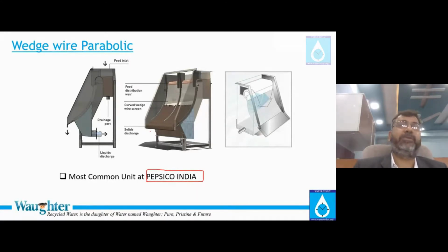If you identify the COD potential of those skins, we are typically talking about a COD reduction by screening alone of almost 6,000 milligrams per liter. So you can compare a waste sample before screening and after screening. And this potato skin is very easy to accumulate on the parabolic screen. So typically you will find the food industry, the grain industry, the Horlicks producers, the Bournvita producers using this kind of parabolic screens, typically not used in our sewage treatment plants.